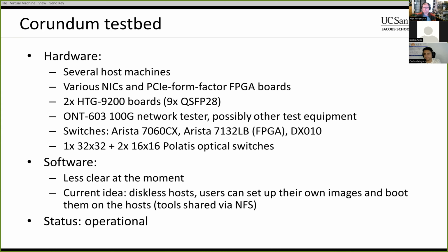Yeah, right. Okay, but there are no modifications on the wrappers for the 100G? Yeah, I didn't make any changes to the wrappers. This is just in terms of the MAC and PHY core logic itself. Okay. Since the wrappers, there's not all that much in there, right? You've got the transceivers, and the wrappers are mostly management logic for the transceivers and clocking and whatnot. So there's not much there that really needs a high level of optimization, because even though the DRP stuff runs maybe 125 megahertz or something, it's quite slow. So yeah, I think so.